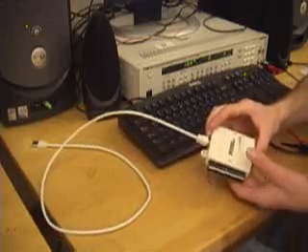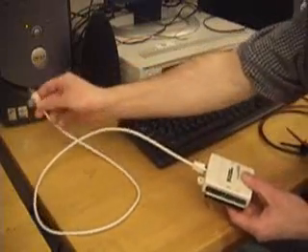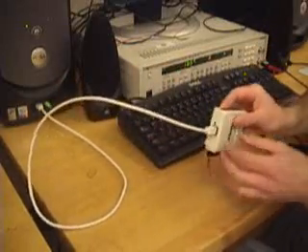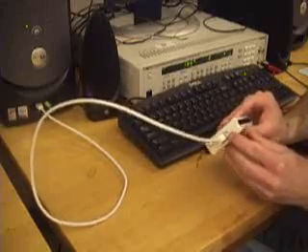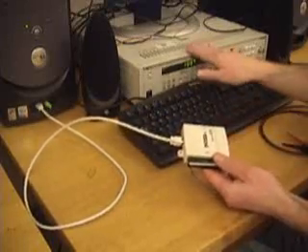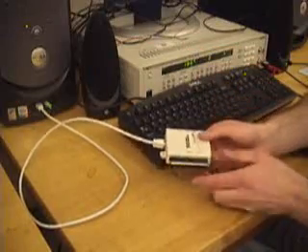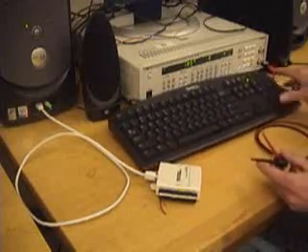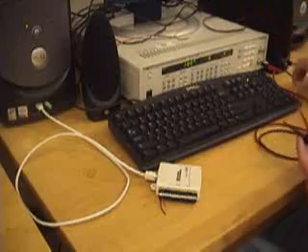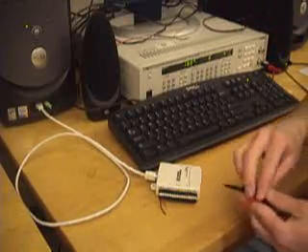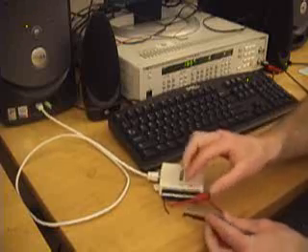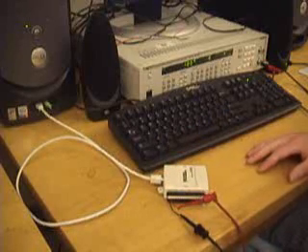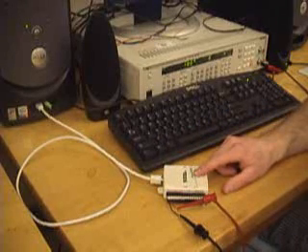To connect the USB data acquisition card, simply take the USB connector, insert it into a USB port, and at that time the green light should be blinking. And to connect the analog signal to the data acquisition card, that's done through these screw terminals. For the first part of the lab, we will be using a signal from a function generator. So we have these wires which we simply connect to the USB card. And now we are ready to create a software program to acquire the analog signal.